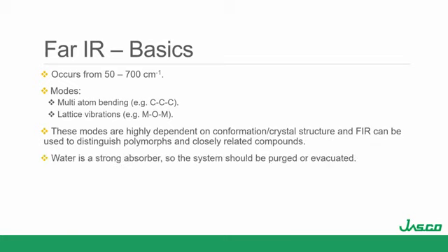Water is a strong absorber, so the system should be purged or evacuated. And I'm a big fan of the evacuation for this, because the water signal will affect your measurement.